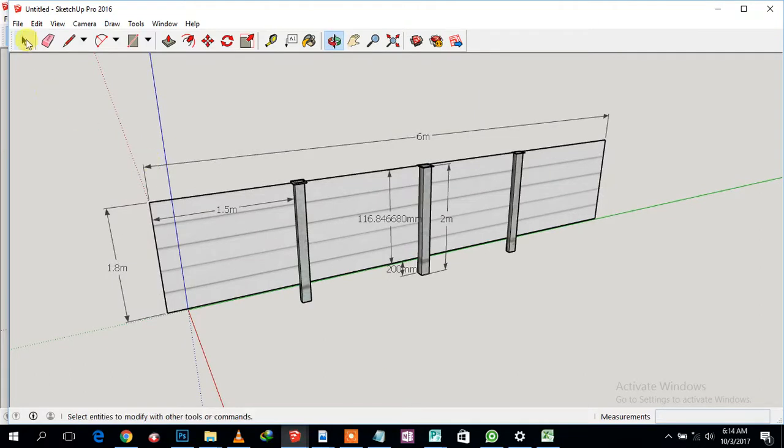The precast fence is the panels. You said it's 5 meters, but we're probably going to have to make it at least 6 meters to get enough gap, because these panels are 1.5 meters. These panels that you put between the pillars, these are the pillars, and these are the panels that you slide in and stack between the pillars. So they are 1.5. You can't buy these long pieces and cut them just because you need to make a 5 meter length.